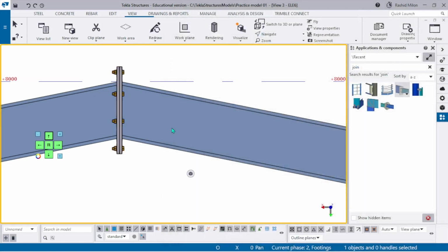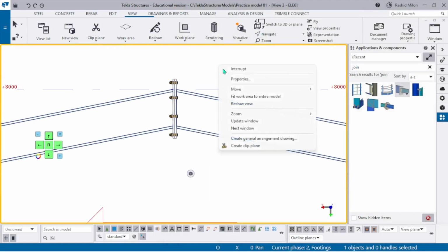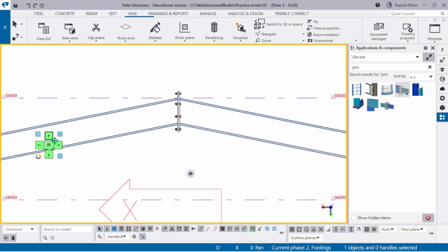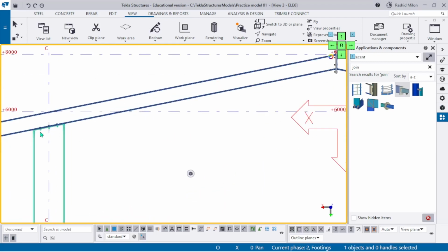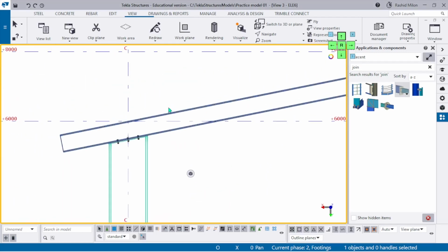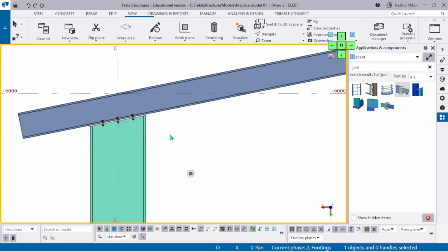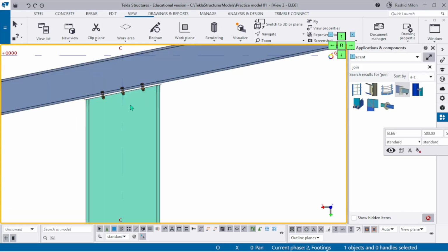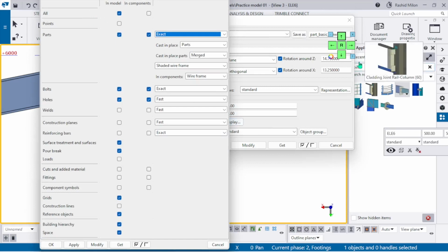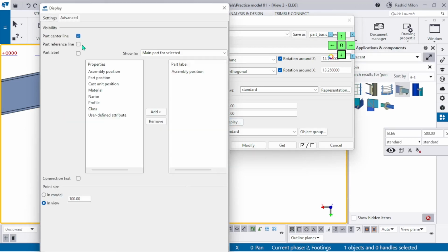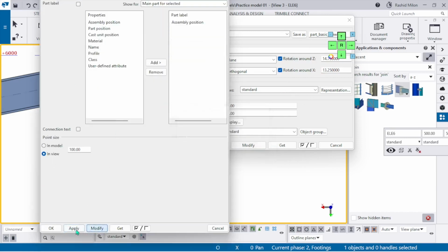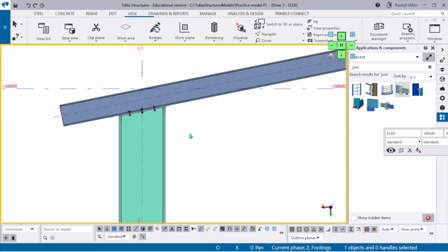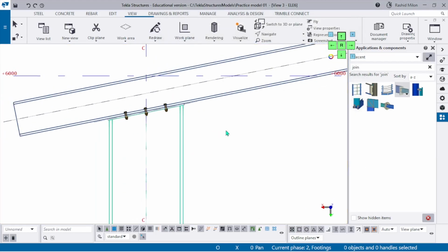Okay, so in this case actually we have to take some reference point for making our C-purlin and our sagrod. Okay, so now we have to make our sagrod first. For making sagrod we can take our center line. For center line reference, we will on advanced option, then center line, advanced display. You go to modify, apply. Okay, you go here, then click our point.